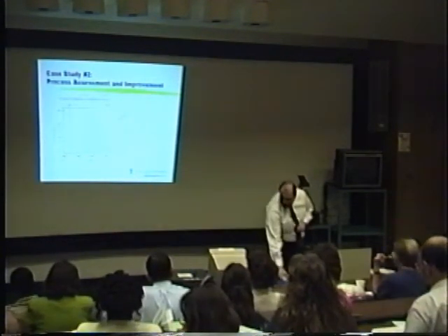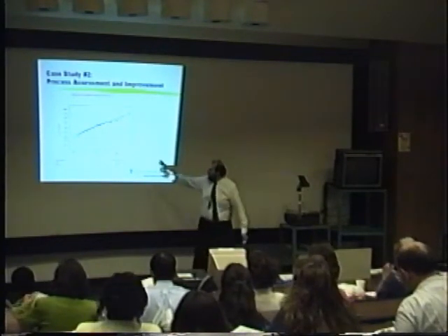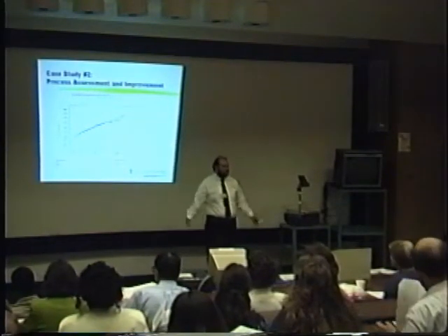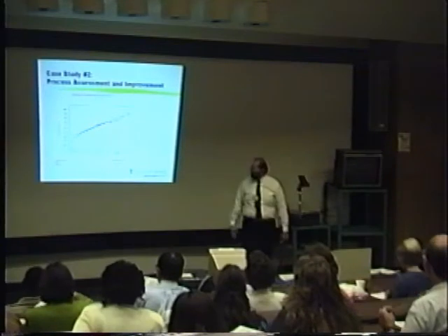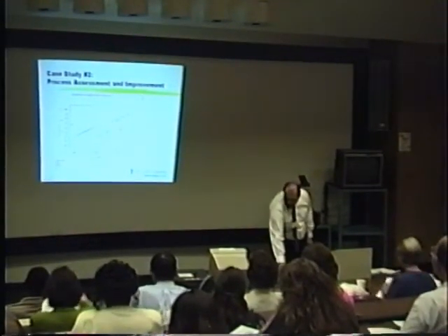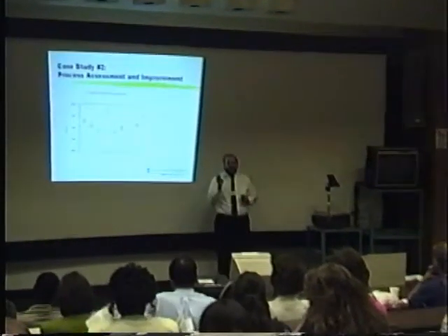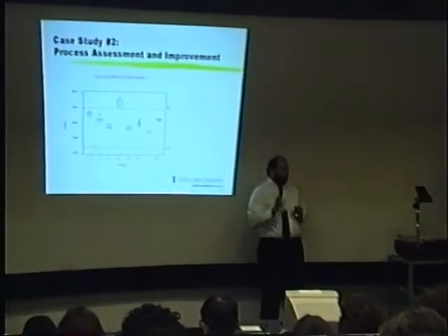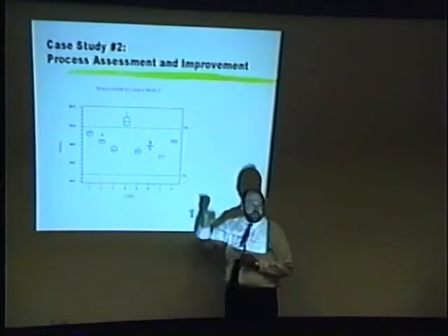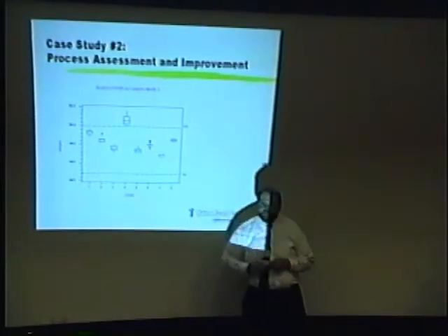So again, here's where we're exploring the data. First of all, looking at a normal probability plot. If the histogram didn't hit you between the eyes hard enough, the normal probability plot, which probably wouldn't even be needed in this case, confirms that we may have some issues here. What was done next was to look at these data on a cavity by cavity basis. There are 8 cavities, as I mentioned. Here we're looking at it a little differently, with the specifications plotted for reference, and a box plot for each of the cavities.